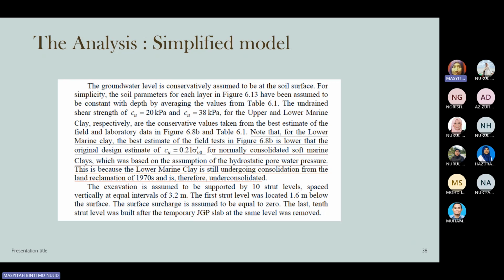Sometimes it has already occurred, but since there is some stress removal and some change in stress history and stress conditions, the consolidation still takes place. So when you have construction near soft clay, please make sure to do soil treatment or soil stabilization first before you do the construction.